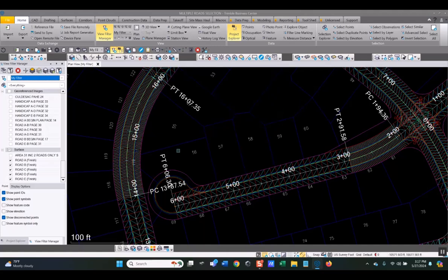When you're using the left mouse key, are you drawing the rectangle from left to right, and it is a solid rectangle? Or are you picking and holding the left mouse key and drawing it from right to left and it's dashed, to use what's called the crossing selection? Any entity that crosses that box, poof, you got it. You can even use the crossing by making a very thin rectangle. Anything that touches that thin rectangle, poof, you got it if it's dashed.